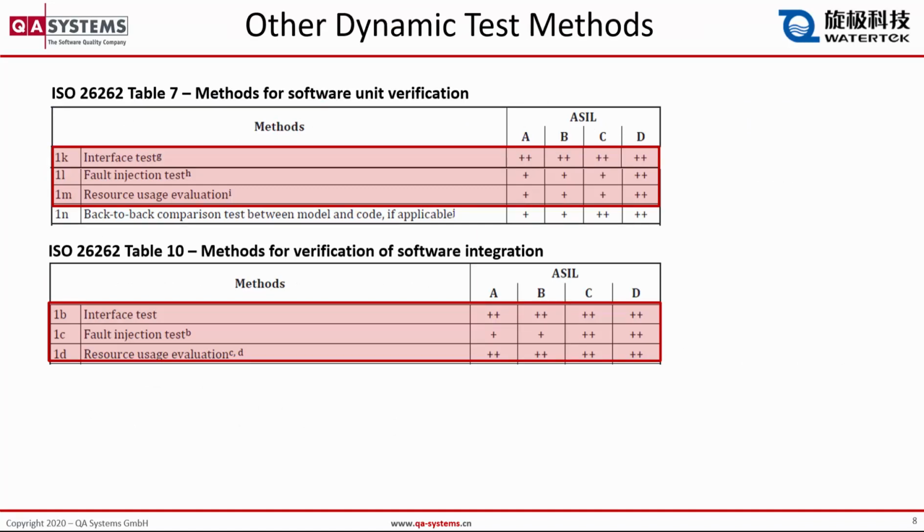Beyond control and data flow analysis, there are other dynamic testing methods in tables 7 for unit verification and 10 for integration. These three principal techniques are interface testing, fault injection testing, and resource usage evaluation.